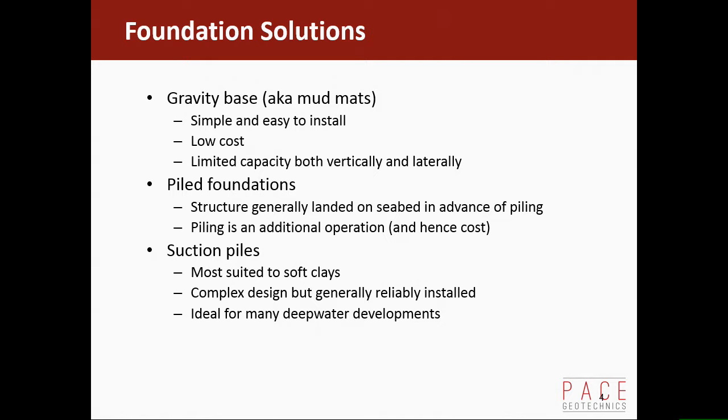And then suction piles, which are most suited to soft clays. They are. But you can use them in stiffer soils, and there's been a bit of research recently which is giving people more confidence in that. But you tend to find them still mainly on deep water soft clay projects. I've got a bit of a case study for you for that. And as it says, ideal for deep water developments.